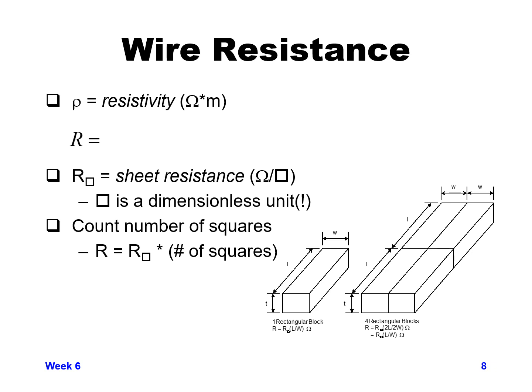So that is a property of what metal is being used and how you actually put it on your integrated circuit. So the value of resistance that you get is your resistivity divided by the thickness of your metal, times the length of the wire divided by the width of the wire.